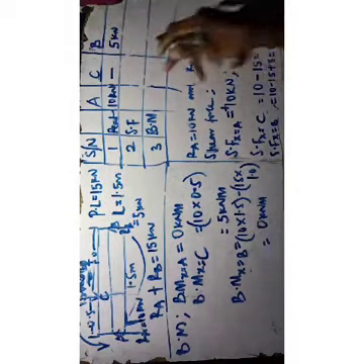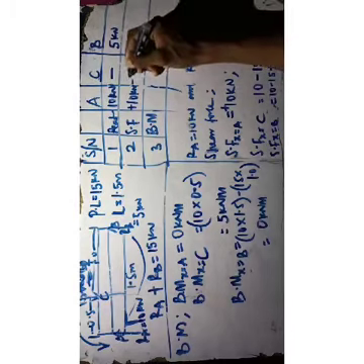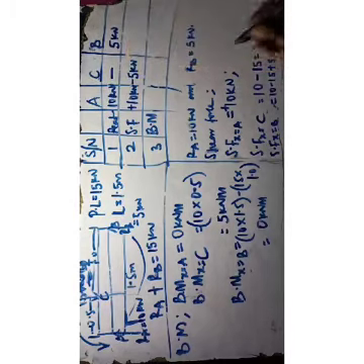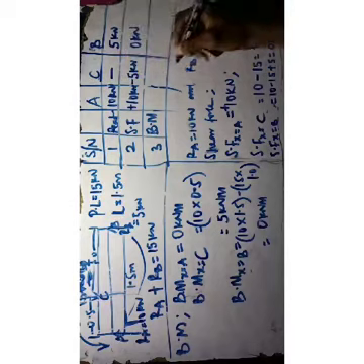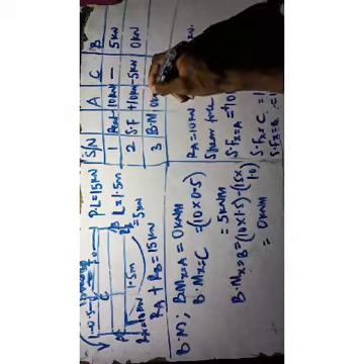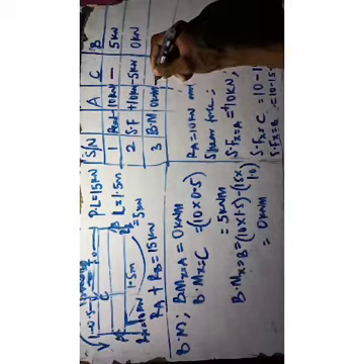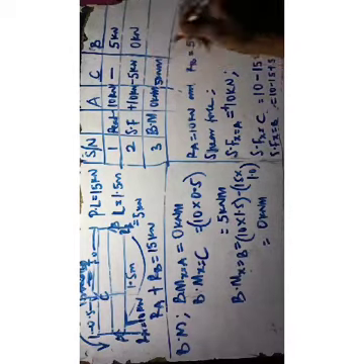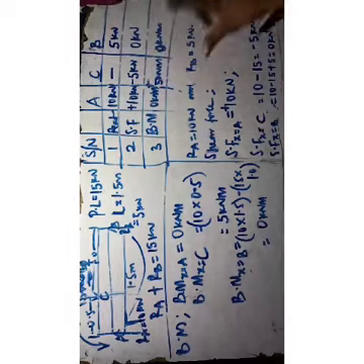Then the shear force at point A is plus 10. At point C we have minus 5 kilonewton. At point B we have 0 kilonewton. Then also bending moment at point A is 0 kilonewton meter. At C is 5 kilonewton meter, and at B is 0. This is positive. Now that is how to tabulate the table.